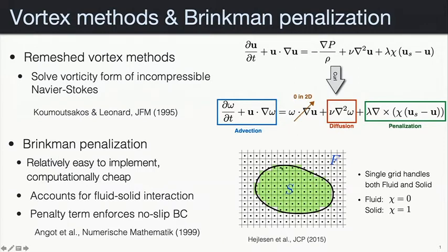If I am in the occupied grid points, in the green cells, after I solve my Navier-Stokes equation, will the velocity inside be the velocity of the solid or not? After I solve advection and diffusion, should I get the same velocity as the cylinder?